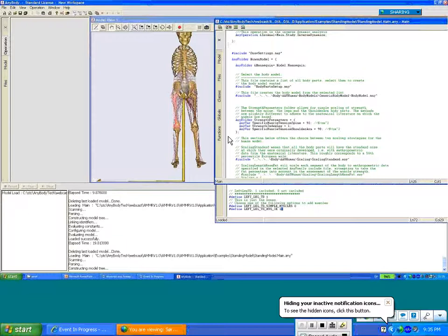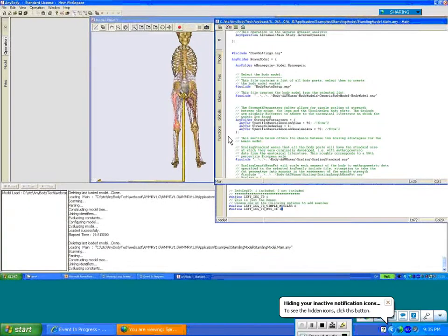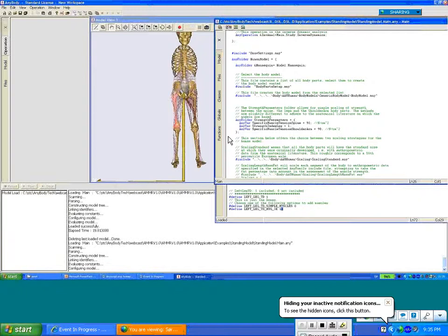Actually, one more thing about the standing model. It has also changed in the way that it's driven. If this had been the old standing model, then we would not have been allowed just to take away the arms and run the model immediately. We would also have needed to add or remove the drivers needed to specify the motion for this arm.